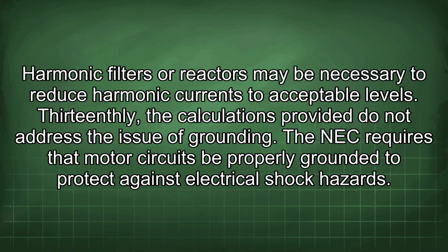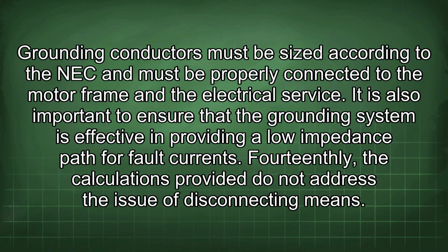13thly, the calculations provided do not address the issue of grounding. The NEC requires that motor circuits be properly grounded to protect against electrical shock hazards. Grounding conductors must be sized according to the NEC and must be properly connected to the motor frame and the electrical service. It is also important to ensure that the grounding system is effective in providing a low impedance path for fault currents.